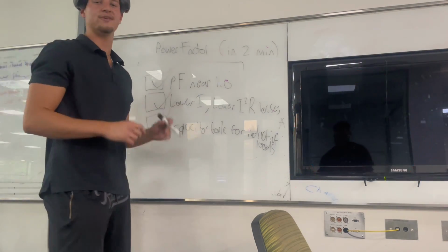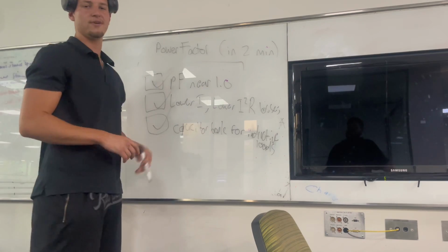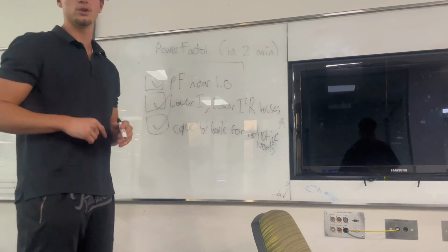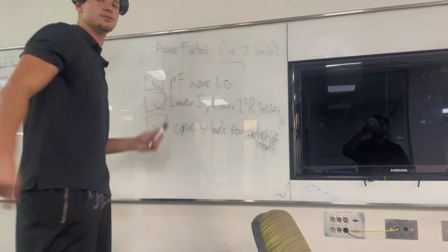Power factor is simply how efficient your AC supply is being used. PF equals P over S equals cos of the angle. Keep it close to 1 with the right correction, and you'll get cooler gear, tighter voltage, and lower bills.